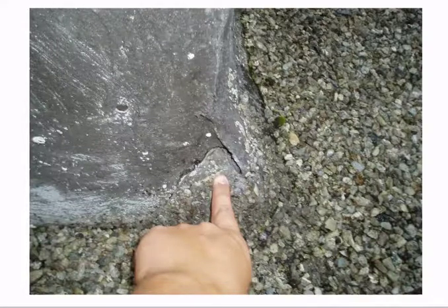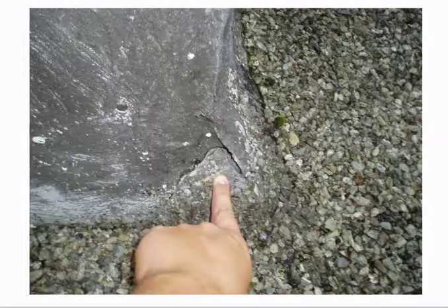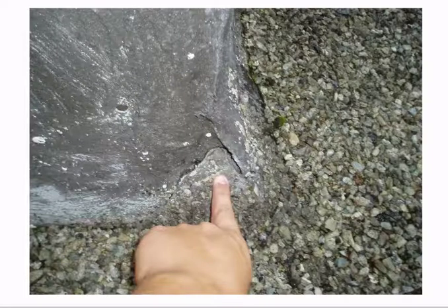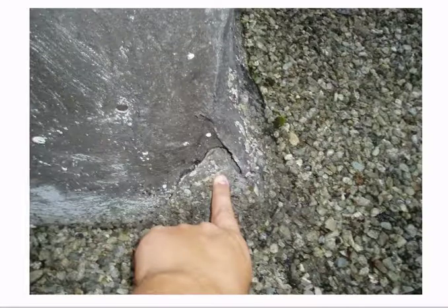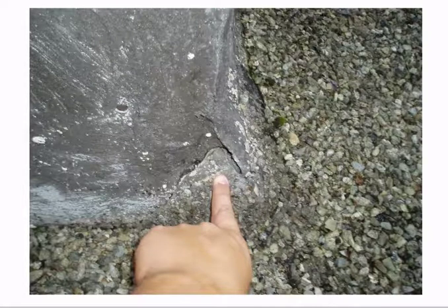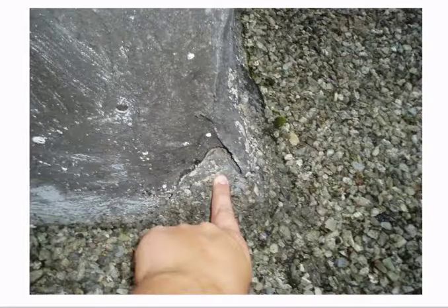But the real fix of that is, you need to spud that gravel back down, expose that asphalt underneath there, and do a patch on that, go down to the roof surface and up onto that flashing a little bit with a minimum of a 3-course system, which is your mastic, your fiberglass fabric, and another top layer of mastic. You can go as far as a 5-course, and that's your mastic, flashing, mastic, flashing, mastic, flashing, mastic. So that would be the best fix on that. And then, if it's aluminum coated, come back after that flashing is cured out a little bit and touch it up. Gotcha.